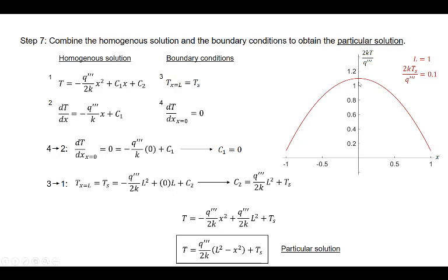Note that the temperature distribution is parabolic. It goes as x squared. The maximum temperature is at the center line. This is the location of symmetry. Did your sketch look at all like this one? You might fix your original sketch now.